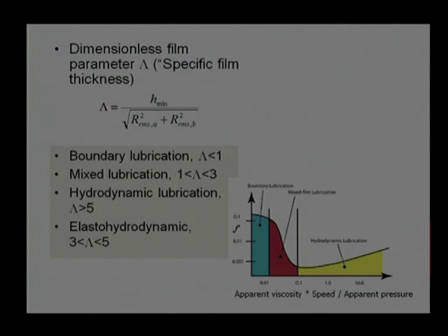The coefficient of friction is going to decrease. It reaches the bottom, the minimum value, and after that again increases. So, if we want to design a tribopair, a machine component, we should prefer this lower portion, where the coefficient of friction is a minimum. That should be our target, and if it is not achievable, then we may negotiate with hydrodynamic lubrication or, to some extent, a mixed lubrication mechanism, depending on the operating condition and the device for which we are working.